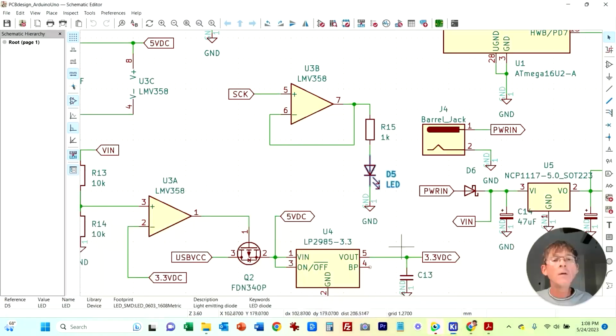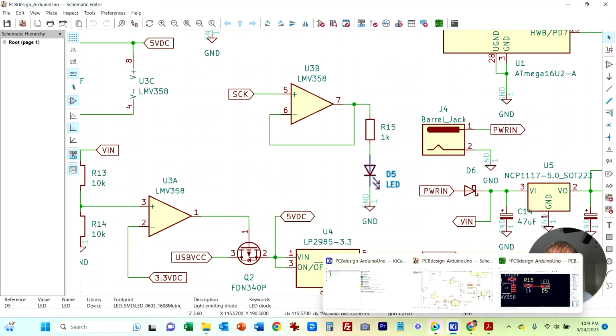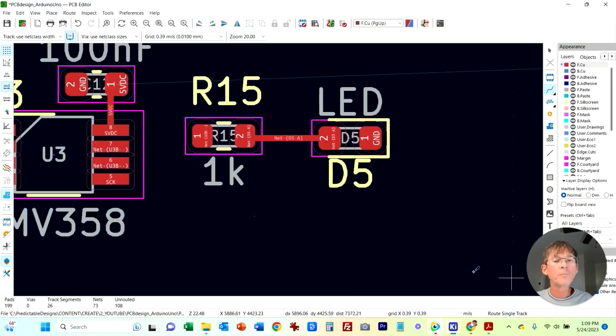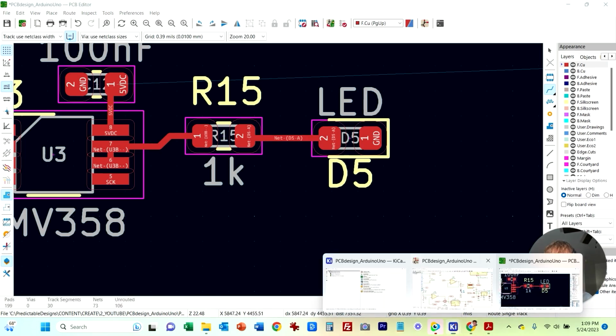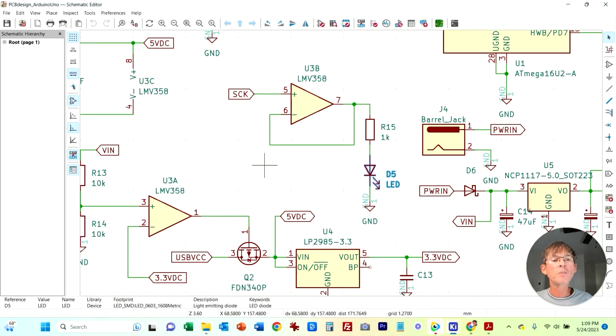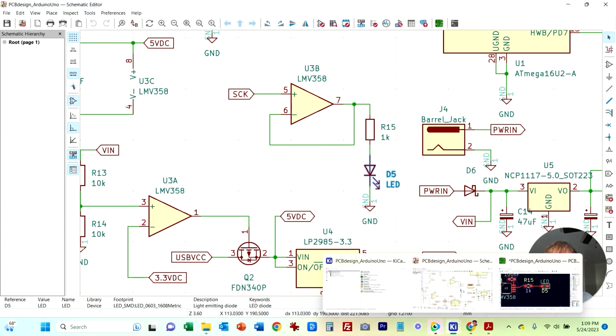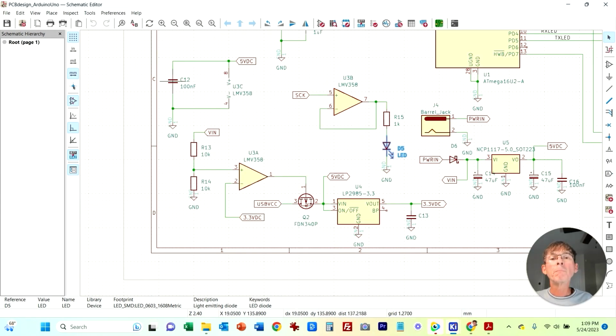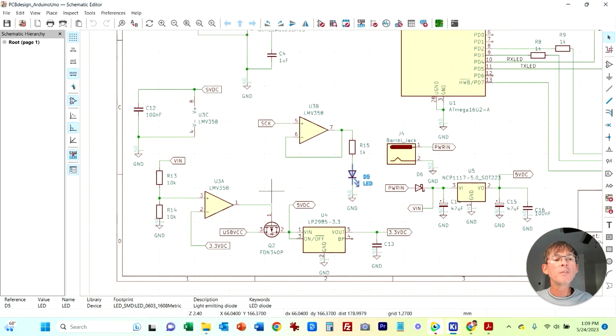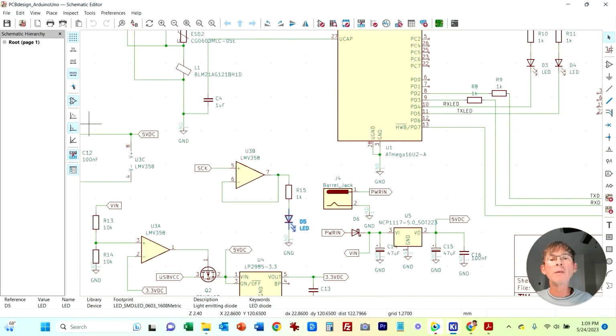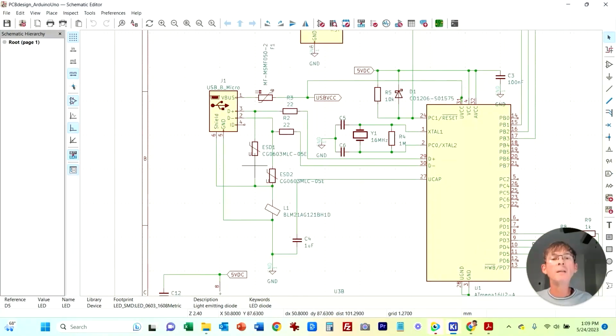And we're going to connect 6 and 7. Let's see. Oh, because they're shorted together. It's unity gain. Mainly 7 is what we're looking for. And we might as well go and short those together. For the unity gain configuration, output just shorts to the feedback. Okay, we've got that. And we have this. Okay, so we have everything here connected.